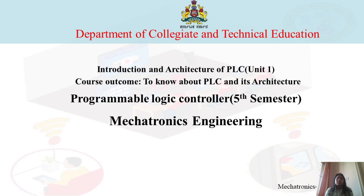Then after that, we have seen how PLCs are classified. First, it is classified into modular PLC and compact PLC. Modular PLC means it will permit the extension of the modules. You can add components like your IO module unit, memory unit, power supply, etc. In the modular PLC, all the components are independent of each other.